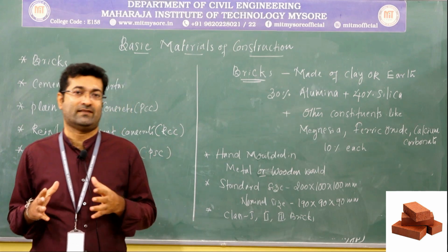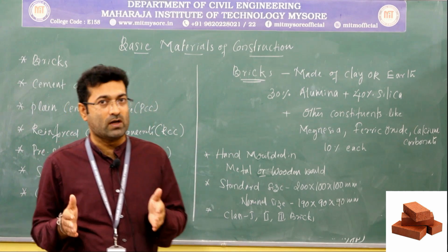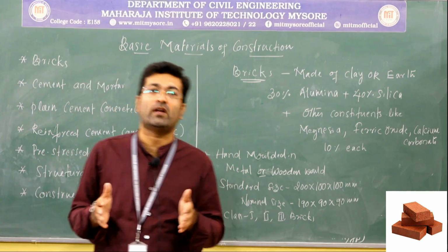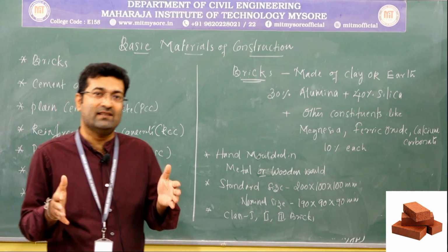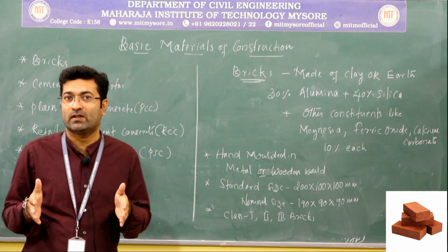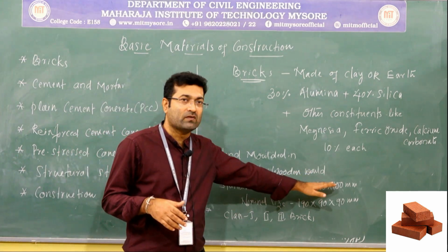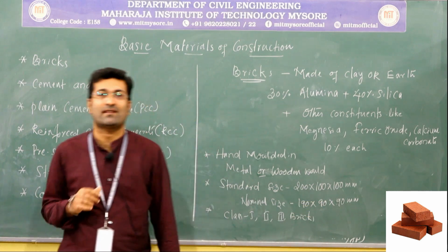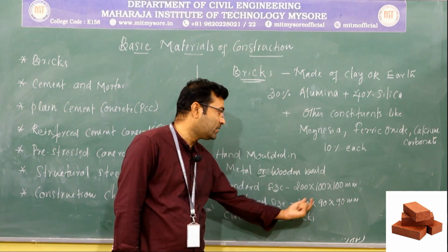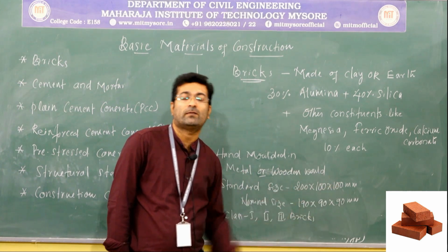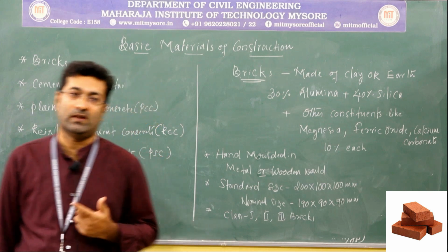What is meant by standard size? Standard size means this size includes the mortar mix which we are using for the bonding purpose. That is, whenever we are using these bricks for the construction of walls, the sizes including the mortar, which is a filling or bonding material, are the standard sizes. To achieve this standard size, we manufacture a little lesser size than that. That is, we usually manufacture the length of the bricks as about 190 millimeter, width as 190 millimeter, and depth as 90 millimeter. So this 10 millimeter gap, we use for the filling material.